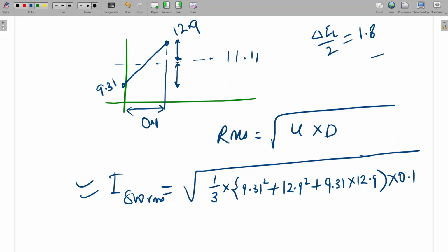See this, if ripple is negligible, then no need to go by this way. If ripple is less, first we can check the ripple. If up to 2 digit or 3 digit decimal is asked in the GATE exam, then we can go by this one. Then it will give the exact value. Otherwise, if ripple is less, we can directly assume this.